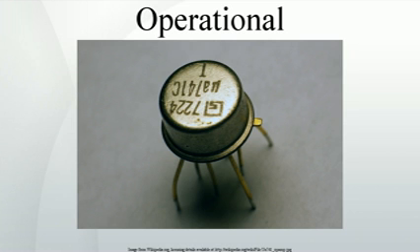1968, release of the μA741. The popularity of monolithic op-amps was further improved upon the release of the LM101 in 1967, which solved a variety of issues, and the subsequent release of the μA741 in 1968. The μA741 was extremely similar to the LM101 except that Fairchild's facilities allowed them to include a 30 pF compensation capacitor inside the chip instead of requiring external compensation. This simple difference has made the 741 the canonical op-amp, and many modern amps base their pin-out on the 741's.